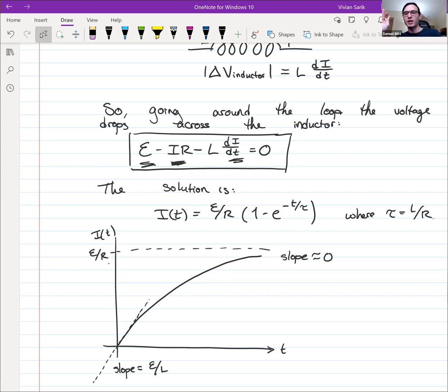It doesn't quite fill up. Well, it kind of does. It will fill up in the sense that it will just have a constant magnetic field after a long time. It does become an equipotential as long as the current remains constant. But it doesn't stop current once it's filled up. It just lets current flow through for free. It doesn't block current. When inductors are empty, that's when they block current. It'll block current from increasing. If it was at 0, then it'll stop the current from increasing instantly.